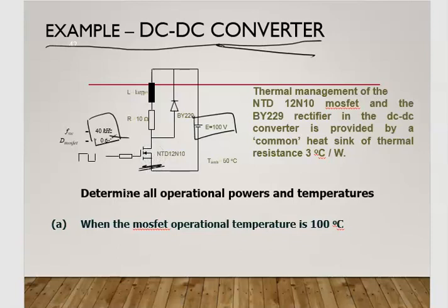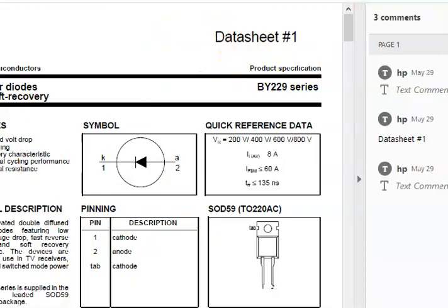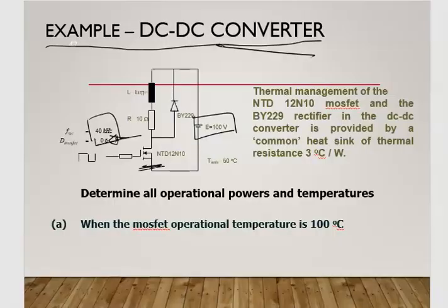As mentioned before, this is the factor that affects the capability of your switch. Even though the front page states how much current the part can withstand, here 12 ampere and 100 volt, when frequency of operation is involved you have to consider their limits.